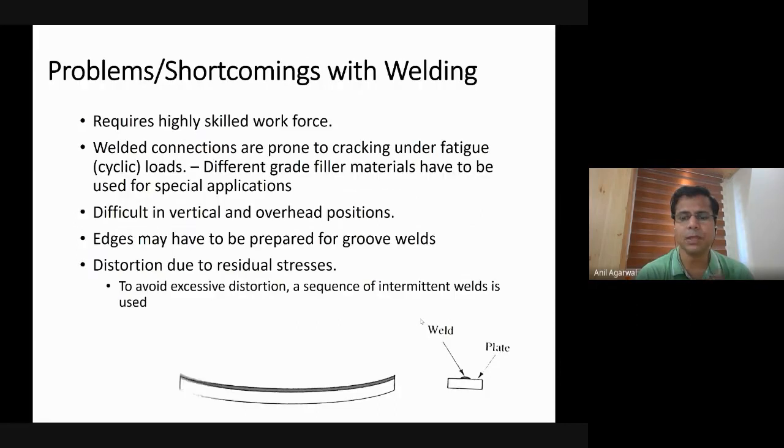There are some, of course, disadvantages also. In comparison, for bolted connections, you have to drill holes, and those holes usually have to be drilled with a very high level of accuracy. So there you require a certain level of skill set. But most of the drilling of the holes is done in the shop, so that is okay. Most of the bolting work, that is tightening of the bolts, is done on the site and can be done by a relatively less skilled workforce.